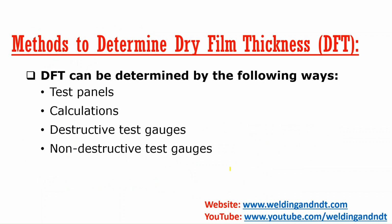So let's start with today's video, and in this video we'll understand how to determine the dry film thickness. Dry film thickness can be determined in the following four ways. First one is a test panel. Then you can determine the DFT by using calculations, by using destructive test cases, and finally by using non-destructive test cases. With all these four methods, you can determine the dry film thickness.